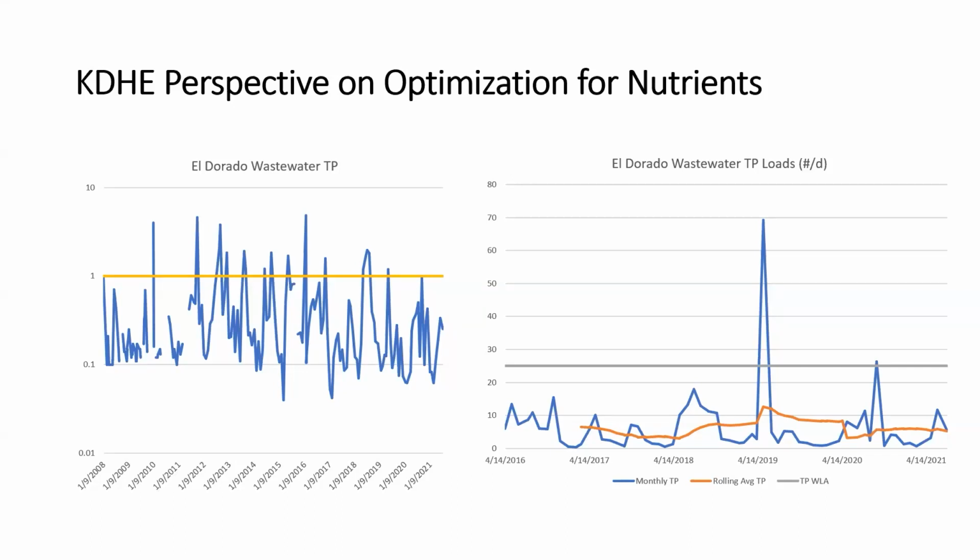Activated sludge, oxidation ditches, sequential batch reactors are all primed for opportunities for optimization. If you're running a plant that's a trickling filter or a rotating biological contactor, that's pretty antiquated treatment technology that is just screaming for need for upgrade in and of itself, and optimization is not the path to do that.